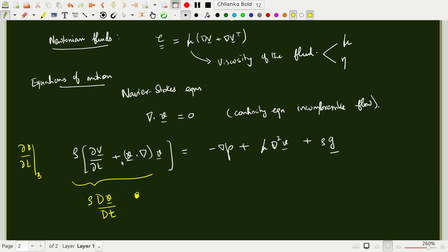But here we are adding the convected component, that is, a fluid particle is not just staying put, it is moving, and you are trying to measure the rate of change of any property like the velocity following the particle. That is this entire derivative, and this is called the substantial derivative or material derivative in different fields of mechanics.